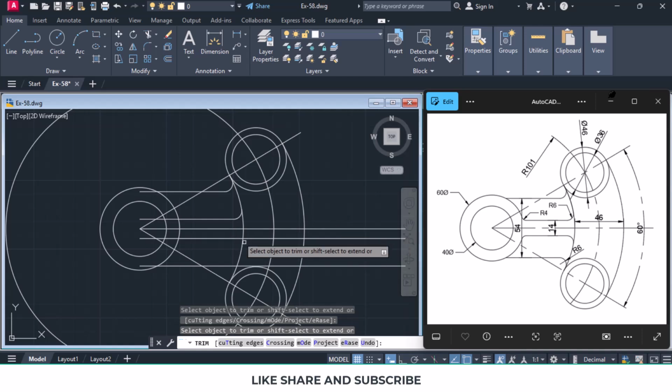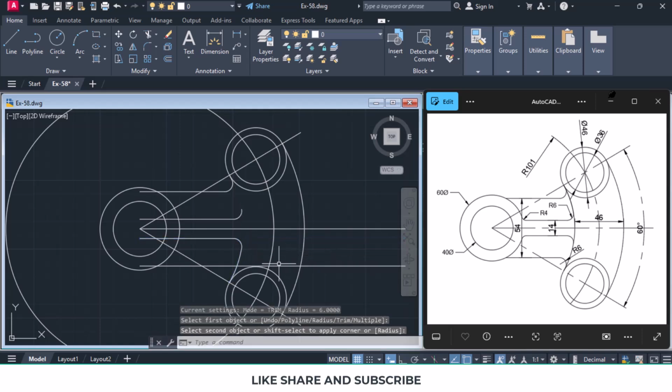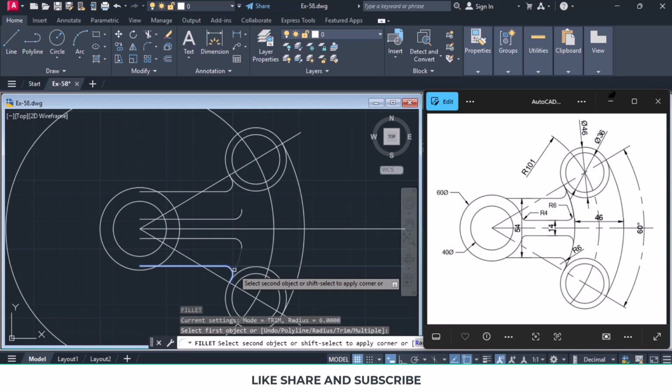Same way over here we want to again fillet at a radius of 6. So F for fillet, it remembers the previous radius 6. So we click over here and we click over here, we get this. And again over here also we want to fillet. So again fillet, click over here and click over here.